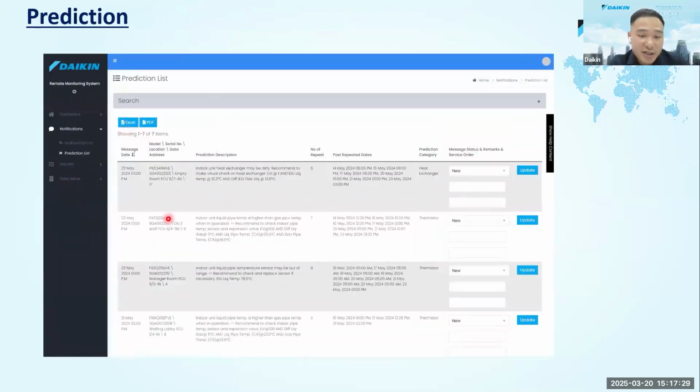So the next one is the prediction. So as you can see here, before the failure happens, we are able to actually predict what will happen. For example, the indoor unit heat exchanger may be dirty, so recommend to make a visual check. So before that error occurs, we are able to sense the abnormality of the equipment. So from there, they are able to save FM work, so that before the thing breaks down, they are able to actually solve the problem.